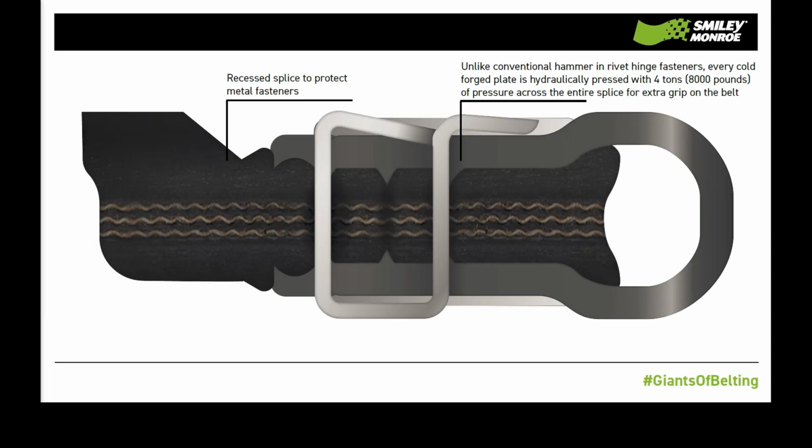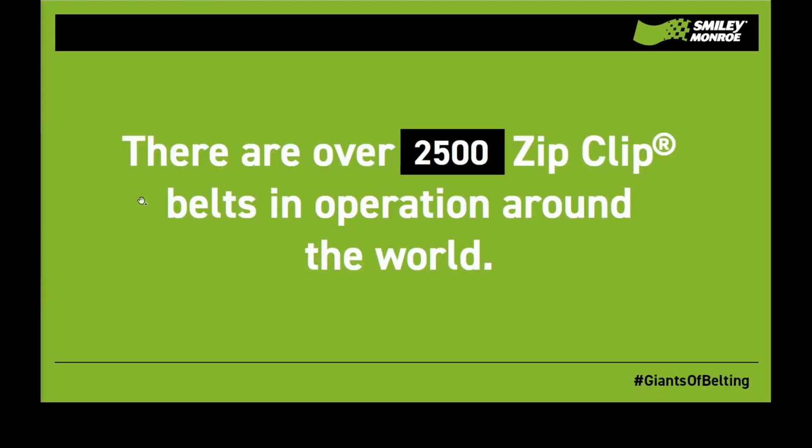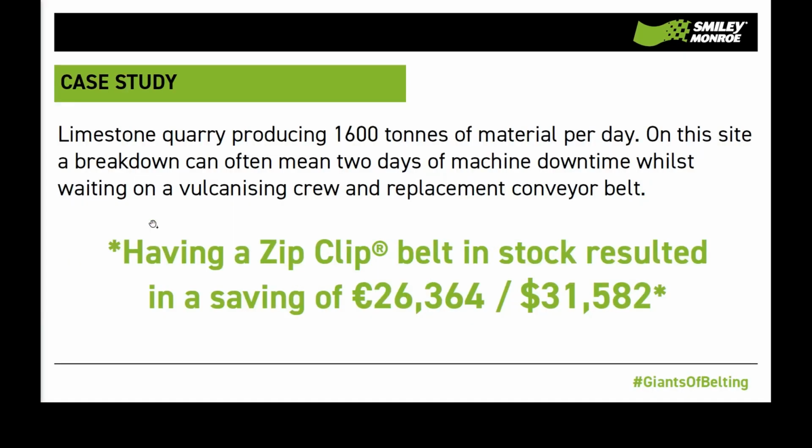Corrosion and wear-resistant stainless chromium steel staples and a stainless chromium nickel armored connecting pin are designed for maximum wear resistance. Factory manufacturing using hydraulic equipment ensures a consistently high quality splice for longer life and superior splice strength and belt straightness compared to hammer and rivet hinge fasteners. There are over 2,500 Zipclip belts in operation around the world.